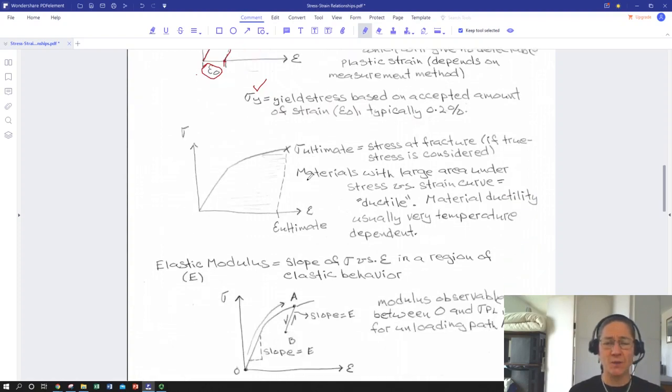Okay, so we've got a reasonable idea of yield, plastic behavior, elastic behavior. So what about fracture? We're generally going to design down in the elastic regime where we're not even going to have to worry about yield, but there are some materials for which yield and ultimate strength, ultimate being the strength at which it's going to break, are pretty close.